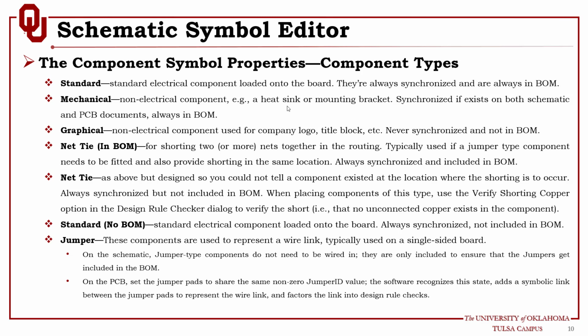It doesn't connect to anything because it doesn't have any electrical property, but it has a place where it will be mounted onto a voltage regulator or transistor or something to cool it down. So it has a physical property on the PCB layout. Now graphical, it can be a company logo, title block, etc., and it's not synchronized, because it's just a graphical representation.